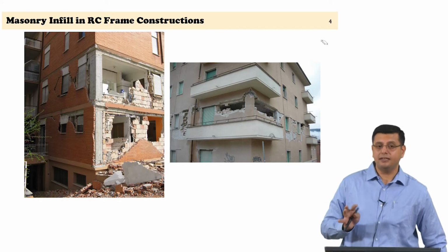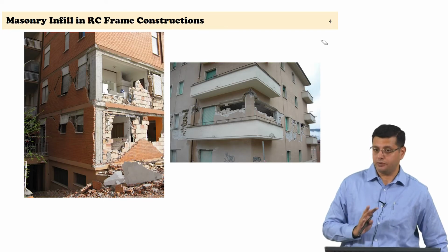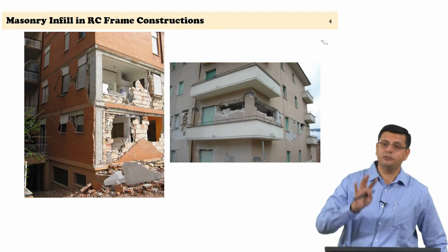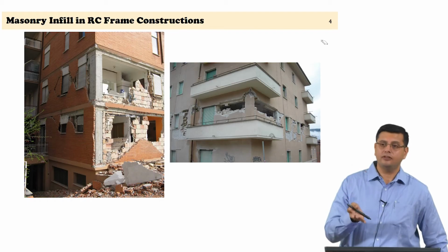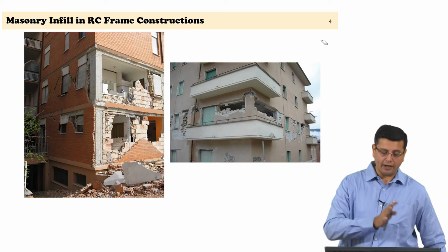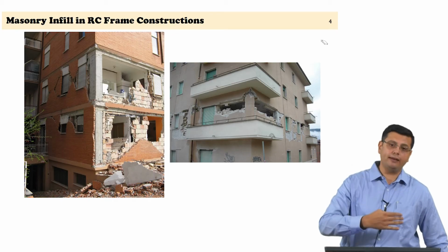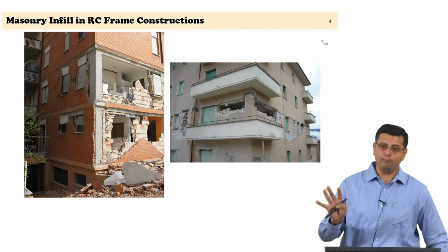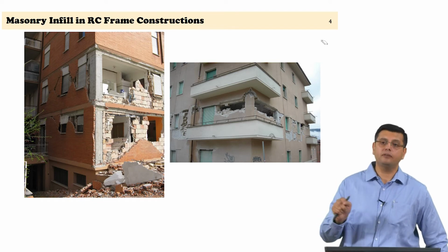Here again you can see that an infill is damaged, but then the size of the infill that is damaged is actually going to be affected by the size of openings as well. So, you might have infill panels which are punctured with openings. So, one has to look at what happens when you have a blank masonry panel, or a masonry panel which is then provided with these openings.